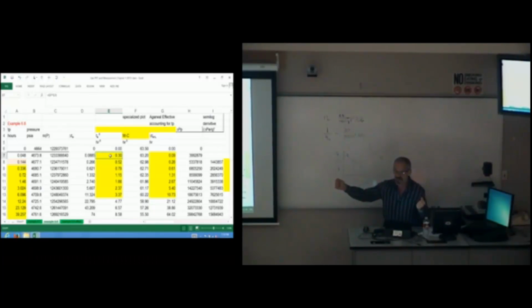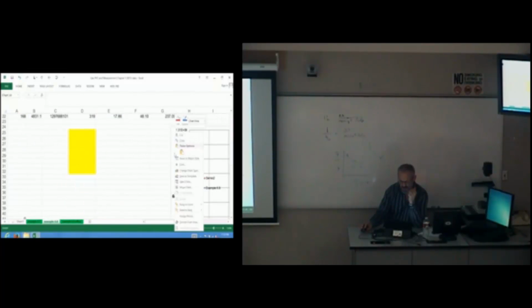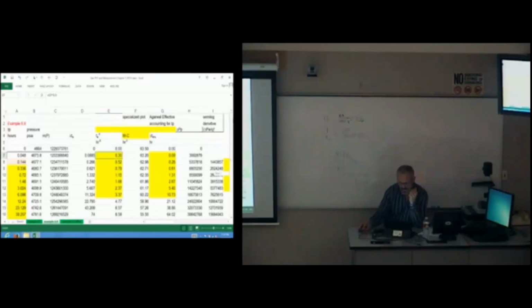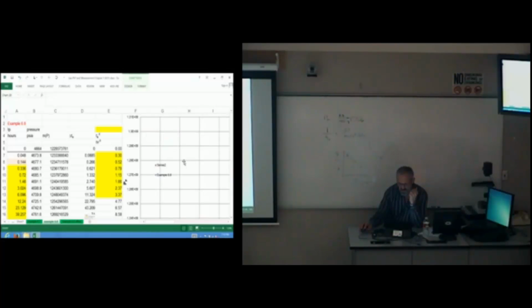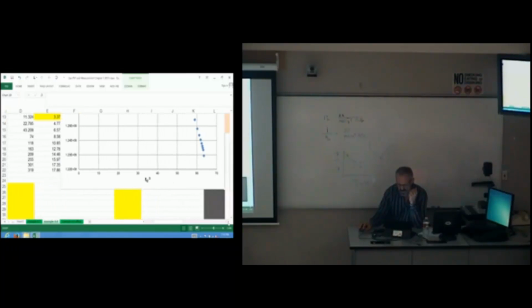And now that I've just increased my T sub P by multiplying it by 24, I should be able to cross-plot the square root of my pseudo time with my pseudo pressure and get an early time straight line, but omit the first 3 points. Let's see if we can do that. Again, I don't know what this graph originally was. We did an MC plot. But the thing I like about the MC plot is it also gives me my extrapolated pressure. Let's just work with that.